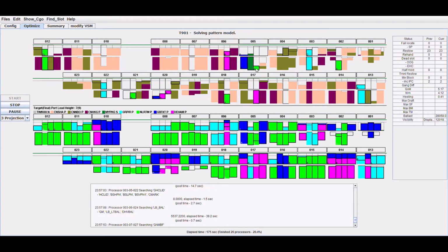Currently, the booking cargoes of the next port are allocated to the block, assigning the cargoes of Shanghai, Ningbo, Hong Kong, and Port Kelang. The engine is calculating the combination of optimal block pattern by repeatedly evaluating stowage factors of each port. For instance, whether the rehandling operation has been minimized, whether the cargo is well distributed along the longitudinal, horizontal, and vertical direction, and whether the ship's stability indicators such as GM, heeling, trim, shear force, and bending moment are acceptable.